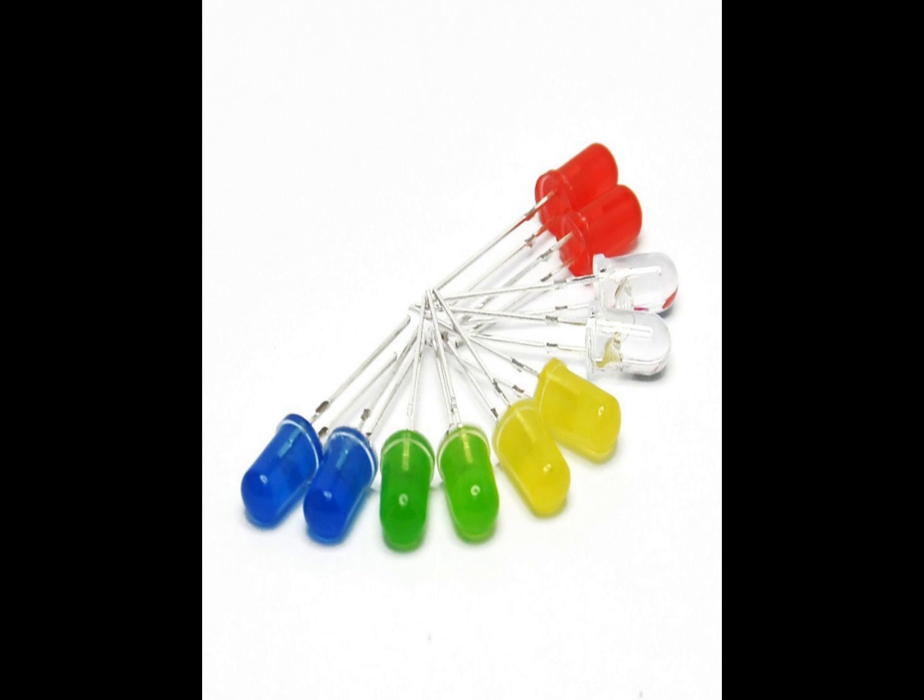We can use the input mode to use external pull-down resistors and much more. But as of now, the output version will be used mostly because we want the pin to perform a certain action. A pin in input mode can weirdly power an LED, but only if we use the pull-up mode. A sufficient amount of current is provided by the pull-up mode to dimly light an LED which is connected to the pin in input mode. If the LED is working dimly, it means the condition is working out. Still though, it is recommended to set the pin in output mode.